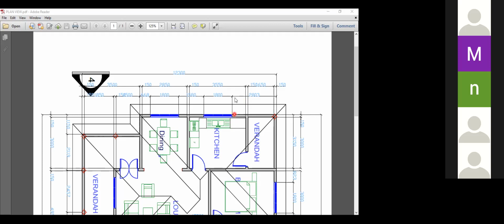In that case, we bring in our ruler and we measure. Then using the scale of the plan, I believe you remember those things in geography, we're able to determine the dimension. That's what we call scaling off. If we come across it as we take off our plan, we shall be able to do it. But mostly we're encouraged to read figured dimensions because they are more accurate than scaling off.